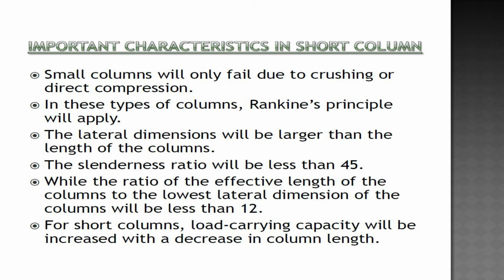The lateral dimensions will be larger relative to the length of the column. The slenderness ratio will be less than 45, while the ratio of the effective length of the column to the lowest lateral dimension of the column will be less than 12. For short columns, load carrying capacity will increase with a decrease in column length.